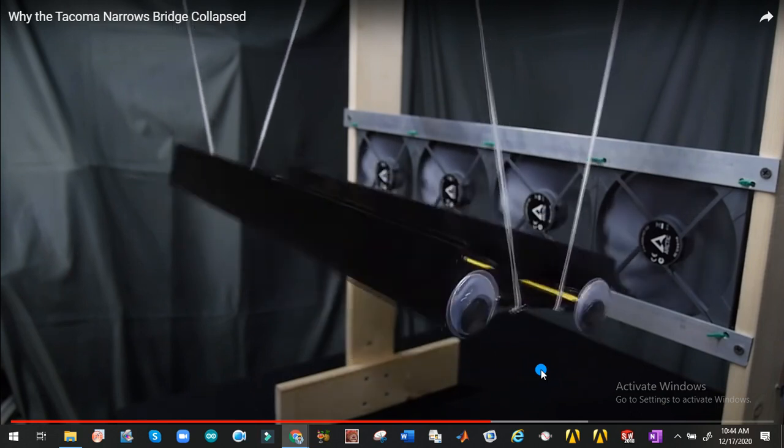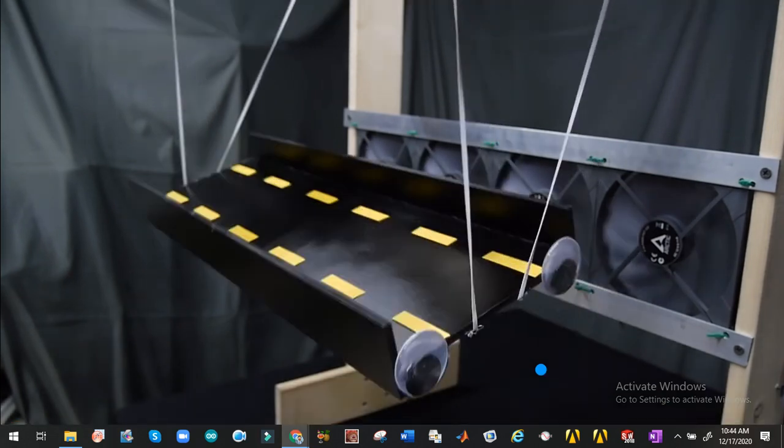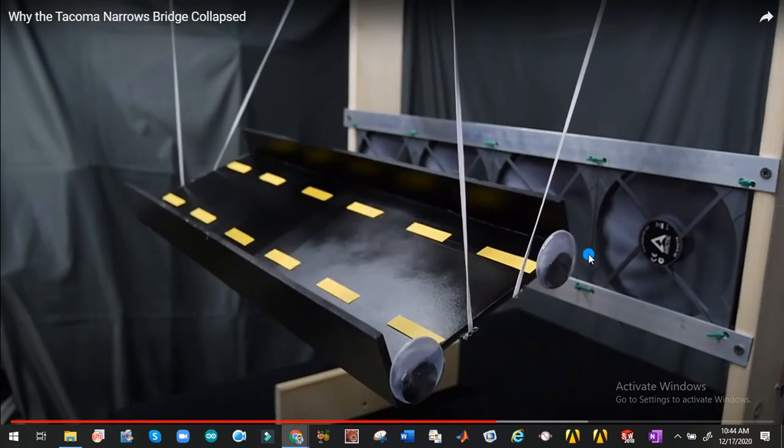Because the periodic forces are self-induced from the naturally unstable aerodynamics. Now if these excitation forces that are twisting the bridge approach a particular natural frequency that has a particular mode shape, either longitudinal mode or translational mode or torsional mode or twisting mode, then whichever mode it approaches, it will vibrate at that mode according to its natural frequency, and if it tries to vibrate at this mode for a long time, then what will happen?